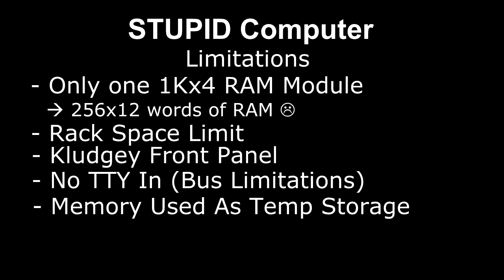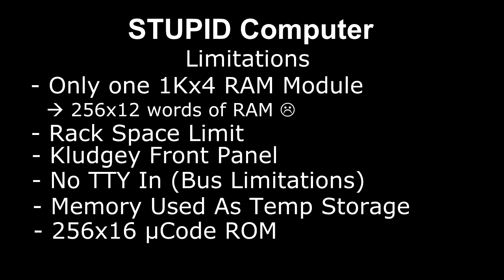Wow, 4K, yeah, that's a lot. TTY input as well as output. Oh, wait, I should go back and mention, the microcode is 16 bits wide. I was allowed 2 ROM chips. They're 256 bytes per ROM chip. It's an old 1702 or something. So I have 256 micro instructions total to implement the whole thing. And I would eliminate that restriction today as well, and build a proper front panel for it as well.